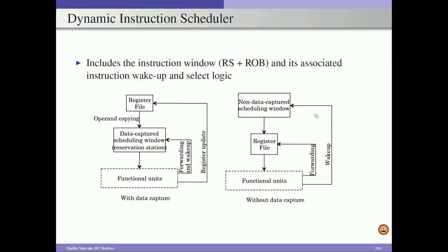As soon as it gets a ready signal here, because R2 is already ready in the instruction, this instruction is now scheduled to the functional unit, and while it is being scheduled on this functional unit, we read the values of R2 and R3 from this register file, and these values will be supplied to the functional unit. So then this instruction will be executed on the functional unit.